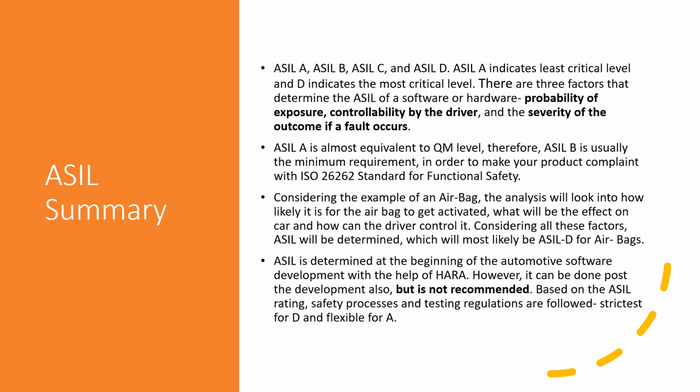Every time you are finding out an ASIL level, it is highly recommended that you start it before developing the product. If we do it in the beginning, then you can prepare everything based on the ASIL level. There are so many aspects which depend on the ASIL level and recommendations based on the ASIL level. So if you determine the ASIL level at the initial time of the product, it would be good. It will avoid a lot of rework.